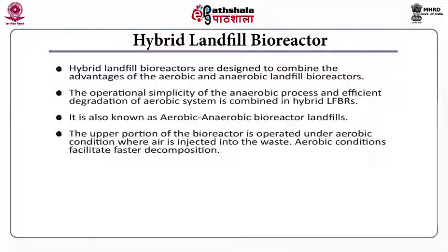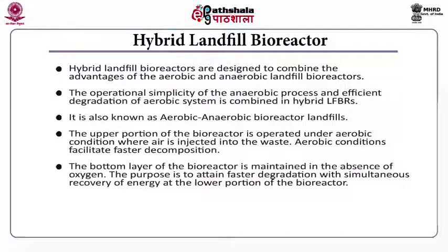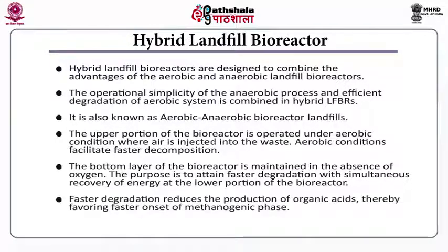The upper portion of the bioreactor will be generally operated in the aerobic condition since it is exposed to the outer atmosphere, where the air will also be injected into the waste. The aerobic condition will facilitate faster decomposition and the bottom layer of the bioreactor is maintained in the absence of oxygen. The purpose is to attain faster degradation with simultaneous recovery of energy at the lower portions of the bioreactor. Faster degradation also reduces the production of organic acids and also favors faster onset of the methanogenic phase.